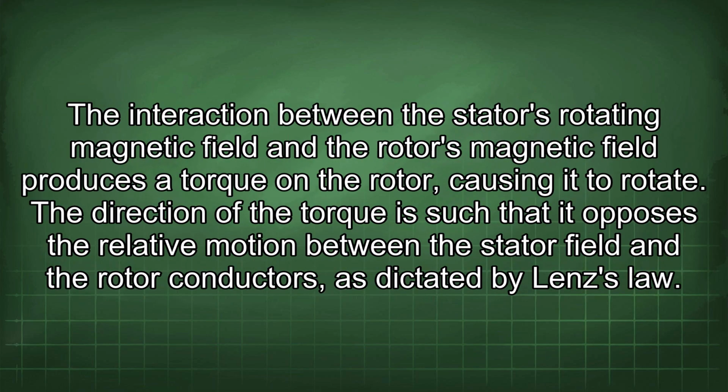The interaction between the stator's rotating magnetic field and the rotor's magnetic field produces a torque on the rotor, causing it to rotate. The direction of the torque is such that it opposes the relative motion between the stator field and the rotor conductors, as dictated by Lenz's law.